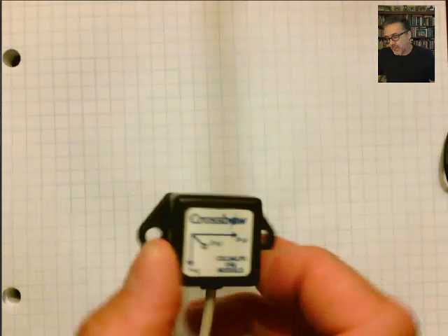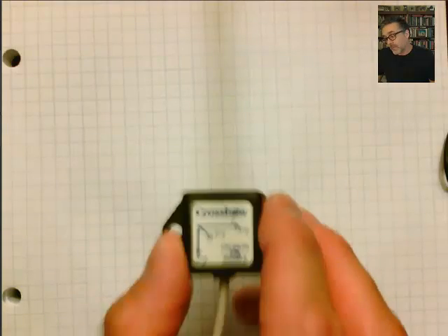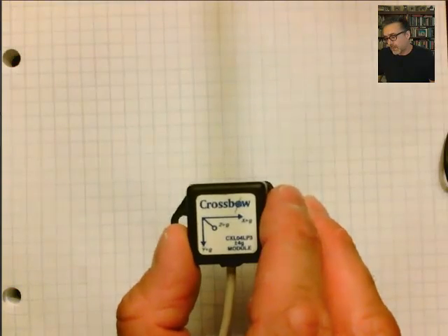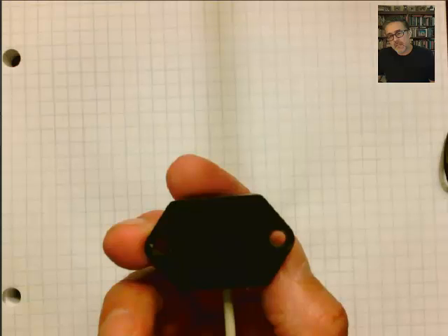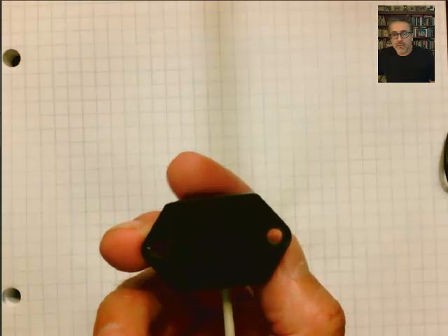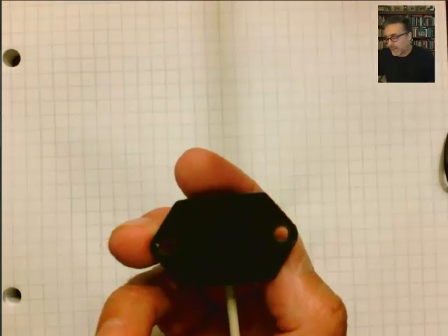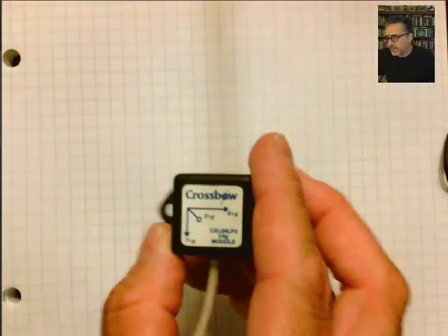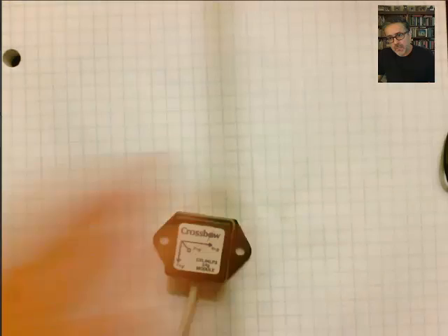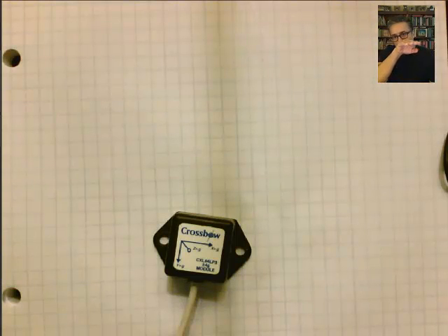So when you're in the field and you say, I'm going to check my accelerometer, hold it, flip it around. That's called a 2G test, right? It's a quick test on your accelerometer. Make sure it's close to what you expect it to be. And you should do that in the lab. Do your 2G test. You'll be reading, say, 3 volts.